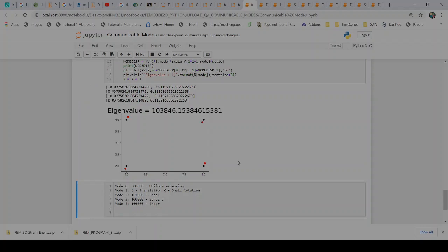I'm going to look at this. This looks again like bending to me. So, bending. This pulls out to the top, so here's tension, and on this side you can imagine there's some compression happening. So that's a bending where you apply the moments on this side. So a moment here and a moment here, squeezing this and pulling here. So that's mode 5, it looks like a bending mode.